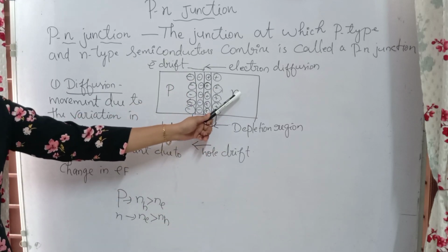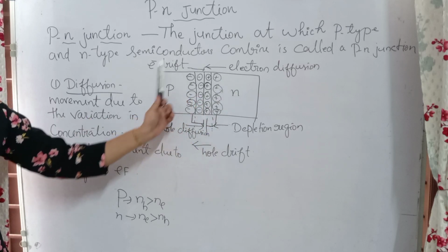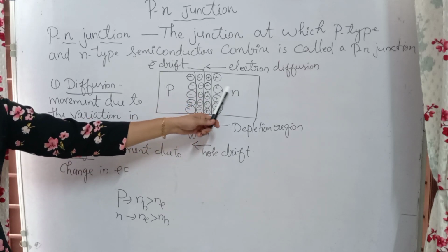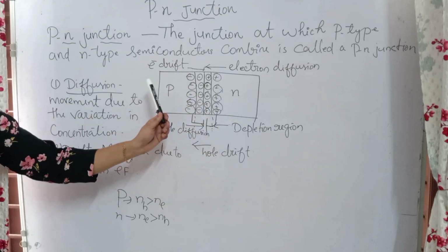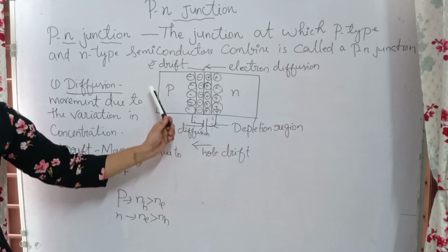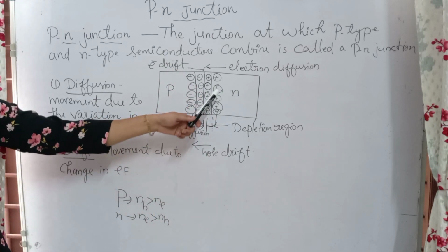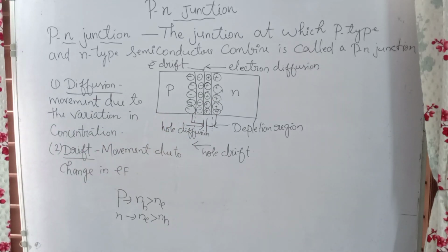The number of electrons will be decreased, whenever that diffusion rate will be decreased, because this barrier will not allow all the electrons to pass through this, and in a similar way it will not allow all the holes to cross through this layer. Okay, so what will happen here? The diffusion current will be decreased.